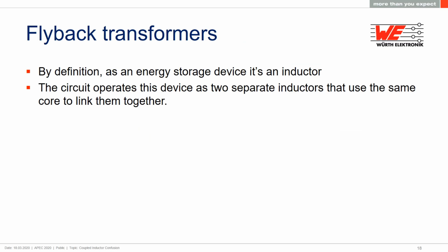The order of the windings, their relationship to each other, also plays a role in this. Flyback transformers. By definition, a flyback transformer is an energy storage device, and therefore it's an inductor. This is a big point of confusion because we all call these devices transformers, when what we really have are two separate inductors that use the same core which links them together.